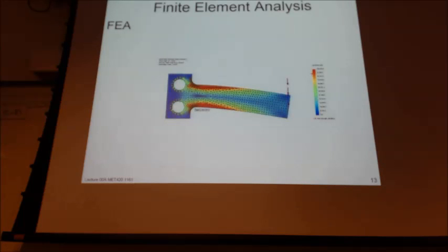And that they are in that linear range of the curve for materials. There are some materials whose linear range is pretty small, and so it doesn't take a lot of deflection to get them outside of that range, and so we have to be careful of those. Plastics and 3D printing would be examples of those.